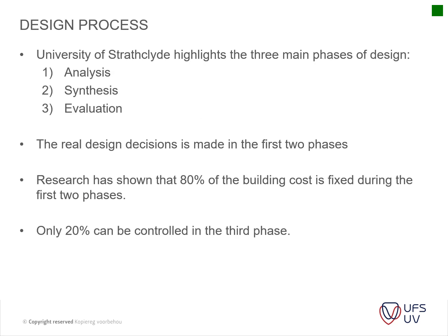Then your design process. Usually you have your analysis, your synthesis, and your evaluation. So you've got your analysis of what the need is, you try and make it material, and then you evaluate it: will this actually fit within the budget? The real design decision is made in the first two phases of the project, and research has shown that 80% of the cost of the building is usually made up in these two phases. Only 20% can be controlled in the last third of the project.